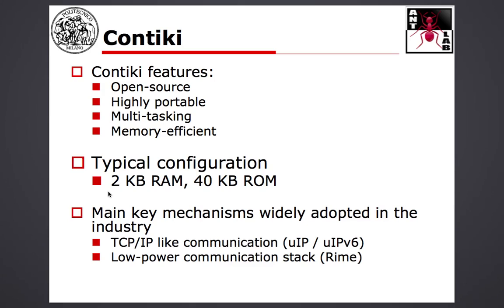Okay, and probably one thing is that in Contiki you have already implemented a set of libraries which can be used for communication, and as we will see, you have the, let's say, TCP/IP stack, or at least a lightweight version of the TCP/IP stack already implemented, and it's called the uIP stack. So basically, you can use your sensor network operated by Contiki to communicate with TCP/IP. Okay, so you basically build on top of the 802.15.4 MAC all the stacks for communication with IP and TCP. Okay, so reliable communication, requests for missing frames, IP addresses. Okay, all this kind of stuff.